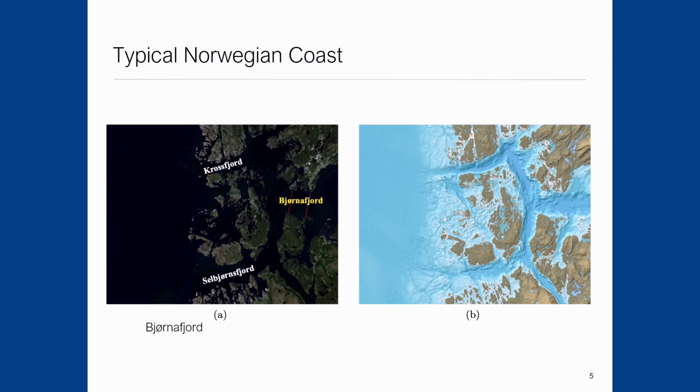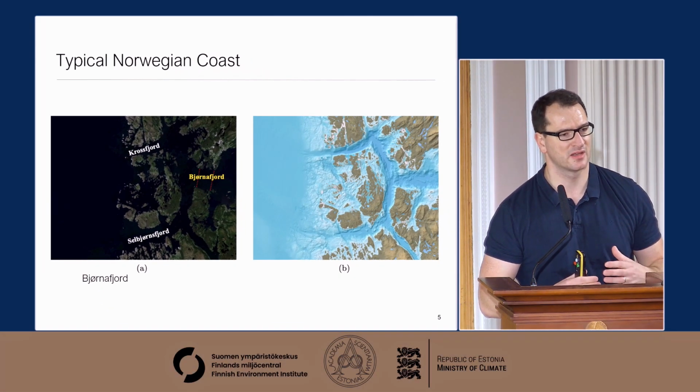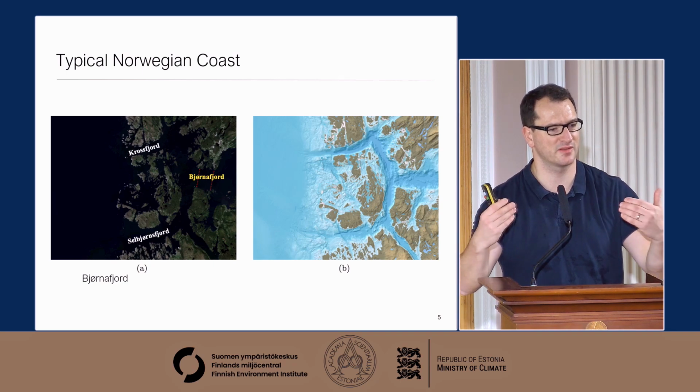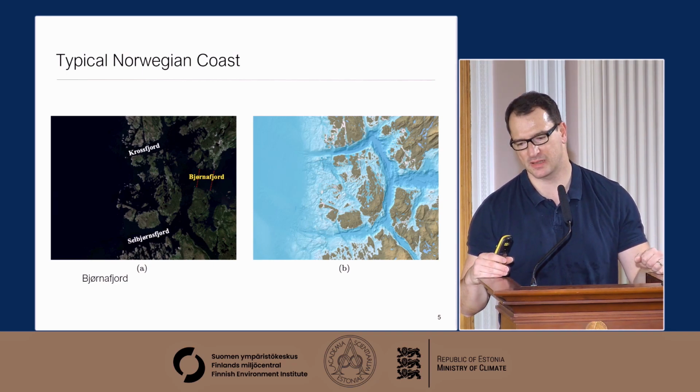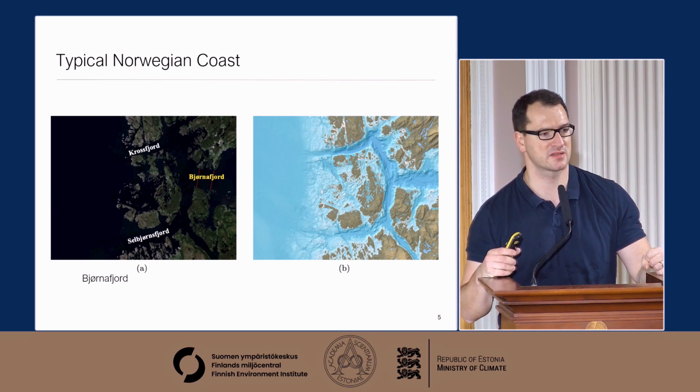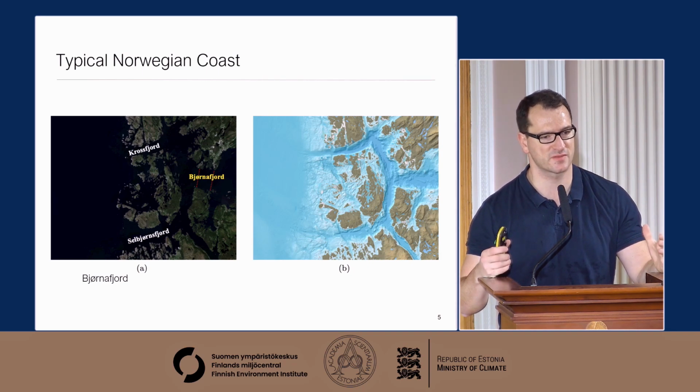On the other hand, spectral wave models like SWAN, we have seen this yesterday, would struggle with the diffraction. On the Norwegian coast, we have a lot of islands causing a lot of diffraction, and so the waves are not fully blocked, but just diffracted around the islands and continue to propagate. And this is why, for a coast like this, it's also very important to consider phase-resolved waves.